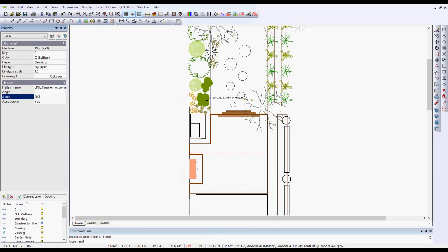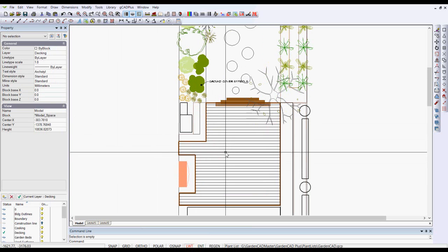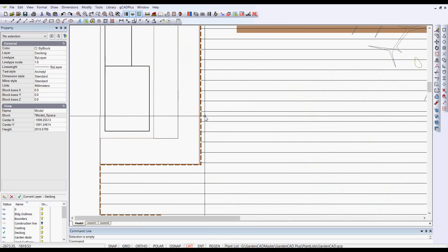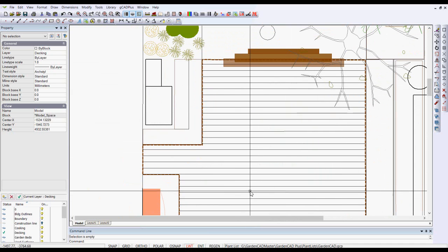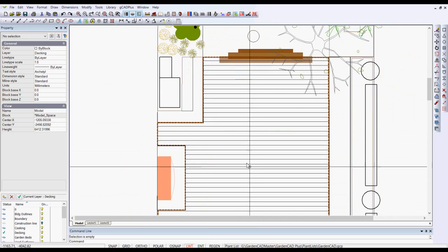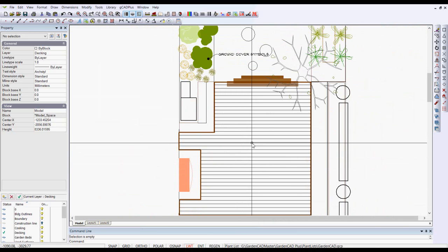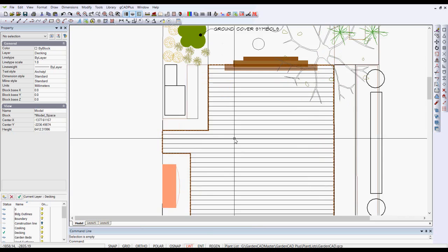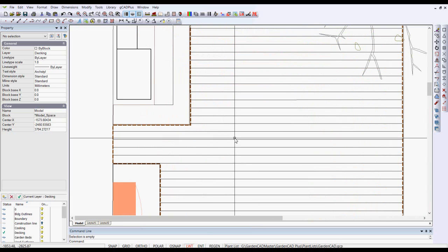Clearly the scale isn't correct. I've changed it to 200, see it come down. I'm guessing about a scale of 50 will give us the result close to what we want. So there's our hatch pattern in. So we digressed a little. We now have a dotted pattern around the area. That may be what you're after, and presumably that's what this drafter was after. So we're slowly improving the layout of this design, and gradually sorting out some of the problems.